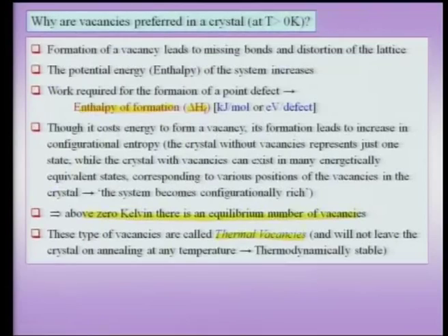Now, suppose I put a vacancy into the system. This vacancy could sit in any one of the lattice positions, and all these would be energetically equivalent. Of course, in this case I am ignoring the surface of the crystal, and I am assuming that all positions are configurationally equivalent. That means by introducing a vacancy, the system becomes configurationally rich, and in this process the entropy of the system increases by introducing this vacancy.